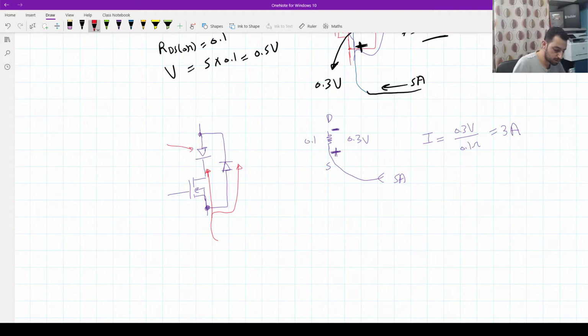That diode is called the blocking diode, and they use it for one reason: to prevent this MOSFET from flowing current backward and to make all the flow go through the external diode. Why? Because they might choose an external diode that has different and lower conduction losses than the MOSFET.